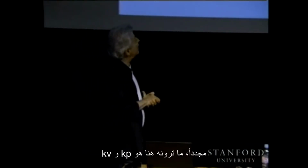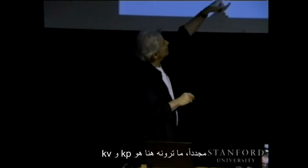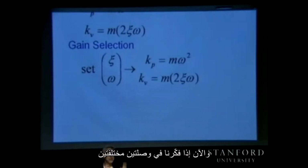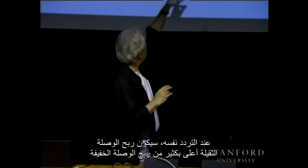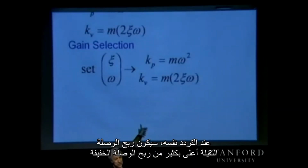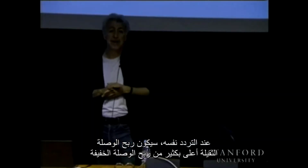But again, what you are seeing here is KP and KV. Now, if we think about two different links, one link that is heavy and one link that is light, m equal 1 and m equal 100, your gain KP, for the same frequency, is going to be much, much bigger for the bigger link.